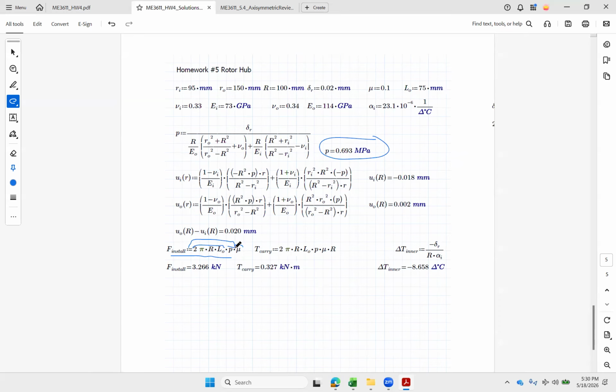And that applies in the axial direction for frictional force, 3,200 newtons. So divide that by 5, it's about 600 pounds of install or removal force. So removal force there, pretty reasonable. We could do that with a press with a crank, like an arbor press kind of thing in a machine shop. Once it's on there, before it starts slipping, it'll carry this much torque, all right?